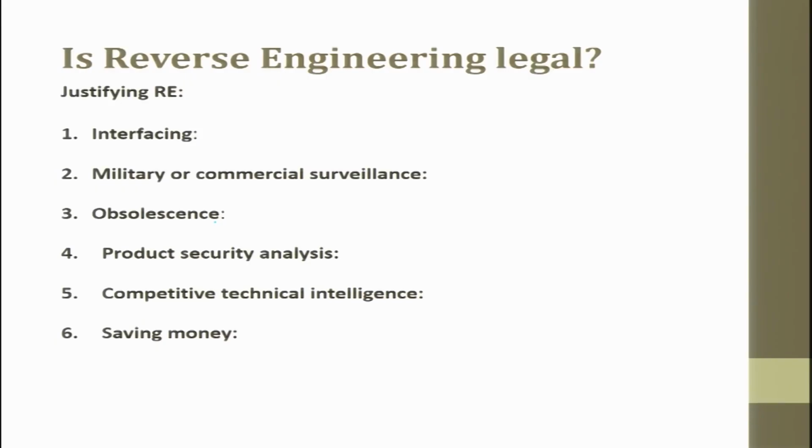No company in the existing world is producing such bearings, which were a peculiar type. It was an obsolescence product, nobody was ready to give us a service. So what we did was, we took the old one, did reverse engineering, understood the parts, then fabricated our own, and put the machine back into action. So for this we do reverse engineering.